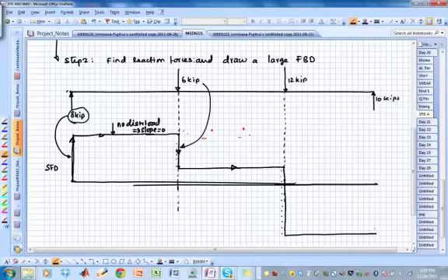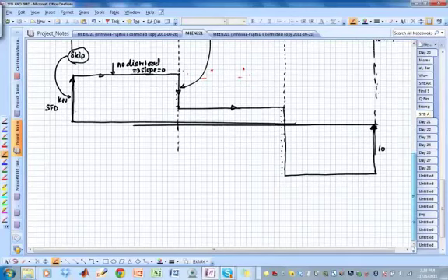When I come to the end, jump up by 10. If you count it, that will be 10. There's your shear force diagram. And this is kilonewtons. Okay. So that's it as far as the shear force diagram goes. We'll draw the bending moment diagram next.